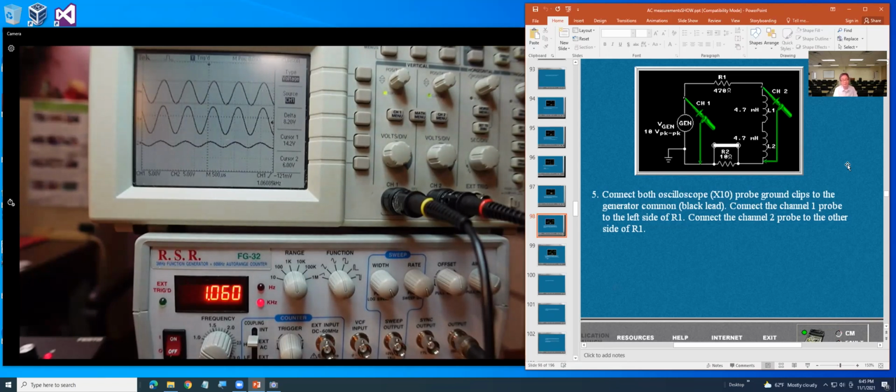First thing, you need to take your oscilloscope and check the scope probe. Both the oscilloscope and the probe have to be by 1 or by 10, the same, for channel 1 and channel 2. Second thing, you must set AC coupling.